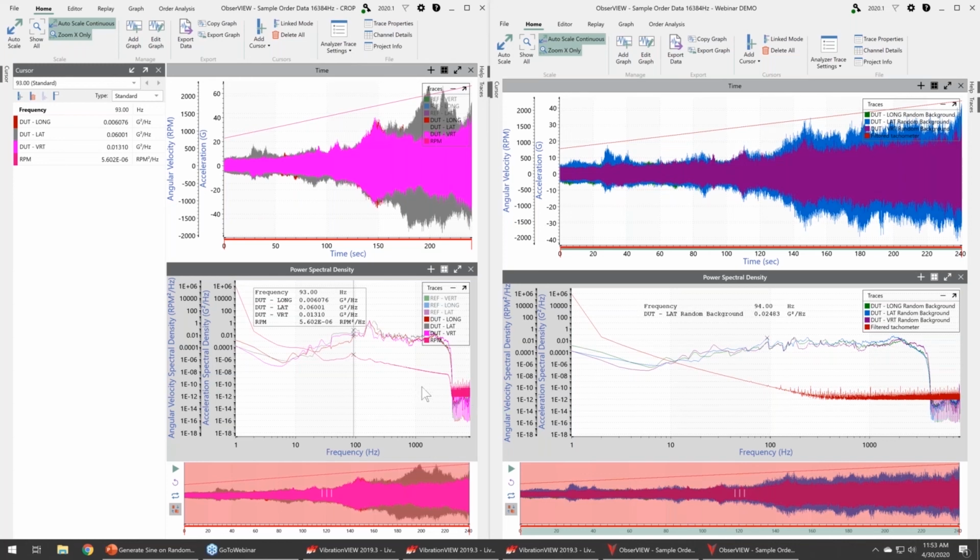How can we decide up to what frequency to be worked upon and up to what order should be worked upon while creating an accelerated profile? The easiest way to start is looking at the amplitudes that are being generated by your Sine-on-Random profile. As soon as your sine tone amplitudes start falling below the overall broadband random, they're really no longer doing anything. So at that point, adding more orders isn't going to benefit you anything.